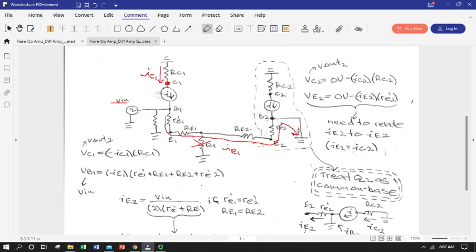So we could write an expression for the voltage at E1 or at the base. We're going to apply Kirchhoff's voltage law of ground minus that first circuit emitter current, voltage drop over little RE2, big RE2, big RE1, and little RE1. So we've got current flowing out of our first transistor over those 4 resistors and to ground here at our second. That's our path to ground.